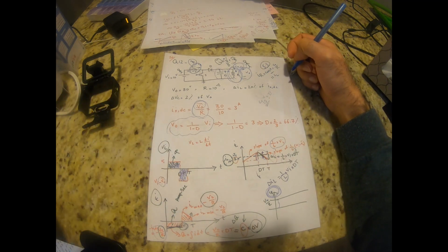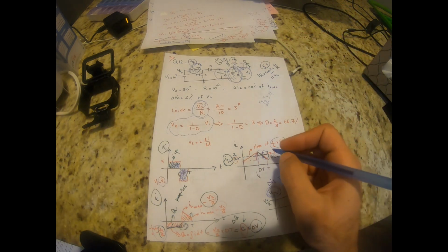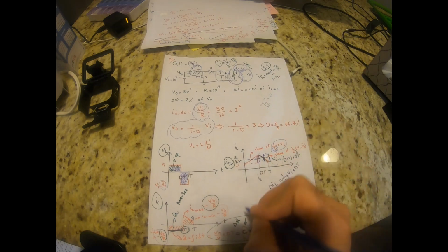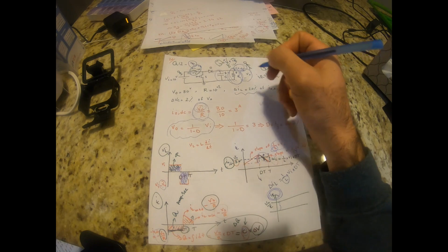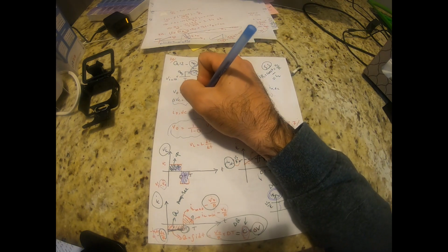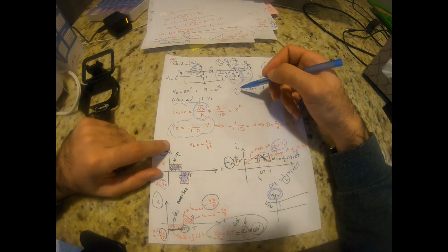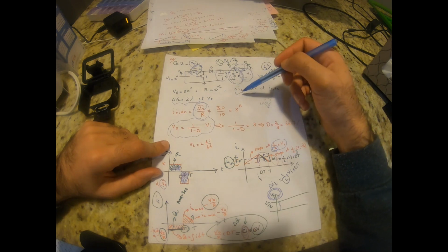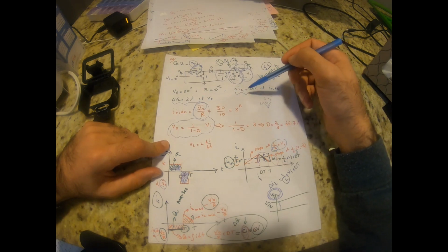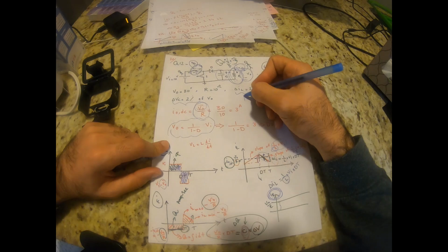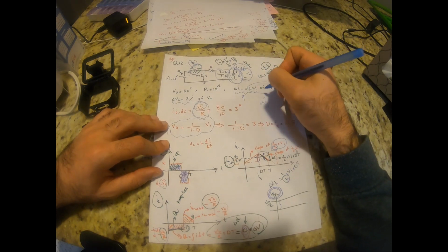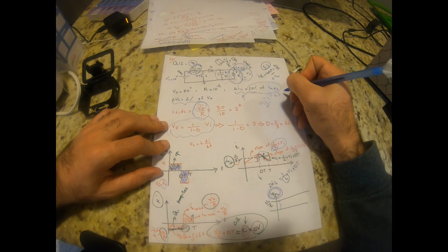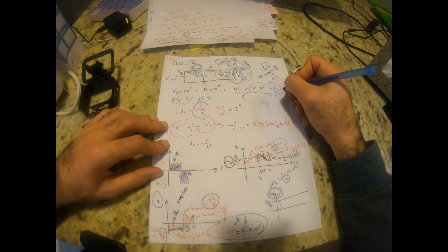So in question 12, I asked you to calculate the value of inductance and the value of capacitance based on the characteristics I gave you for the ripple. If I ask you what's the inductance, you can calculate it based on this. First of all, we said 20% of IO DC, it means 0.2 times VO over R, that's IO DC.